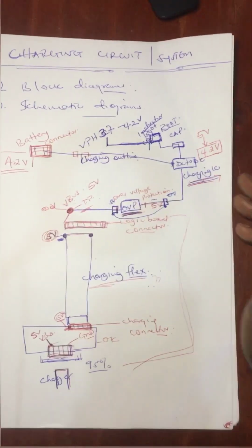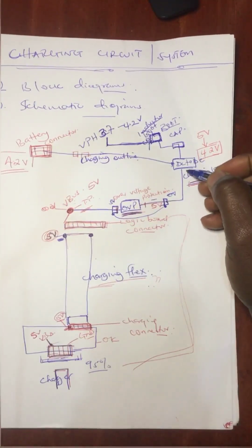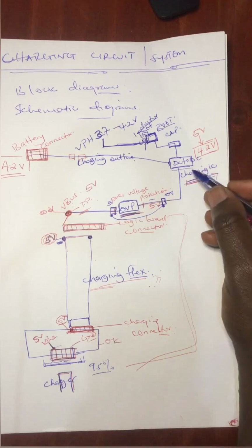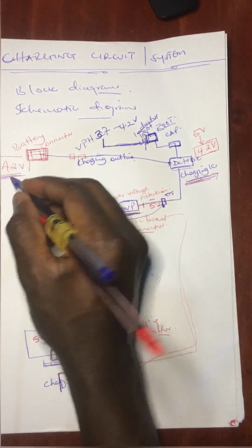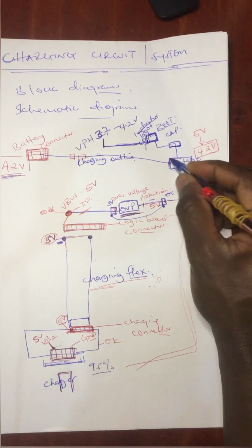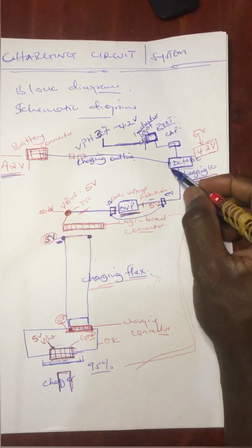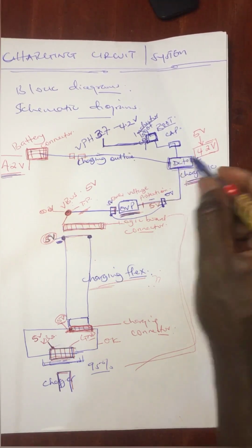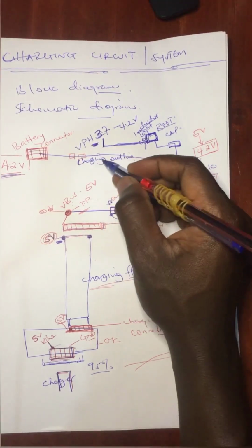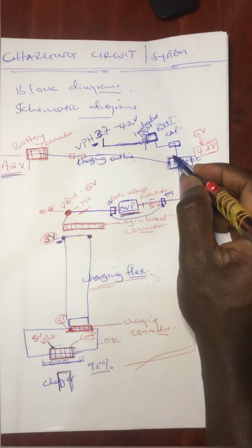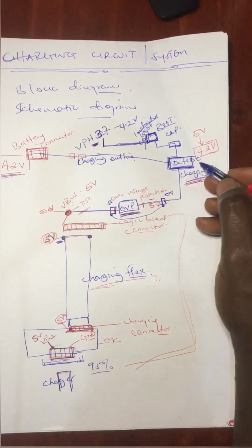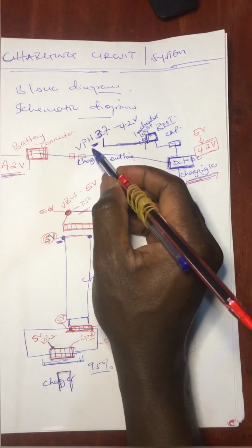Same thing, different way. Now, in case you have the DC to DC IC, or the charging IC damaged, or maybe it has gone bad and it is not giving the 4.2 volts to charge the battery. Now, note me well, in most smartphones, if this IC is bad completely, it will not generate the VPH. And once VPH is not generated, your phone is completely dead. What you have to do is replace or reball this IC.